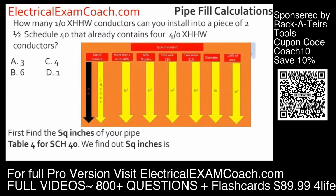When we get there, we're first going to verify that we are in the right type of conduit. Then we're going to come over here to the left, find our size of conduit. Then we're going to come over to the 40% column because we have more than 2 conductors. And we're going to find that for this conduit, it's 1.878.